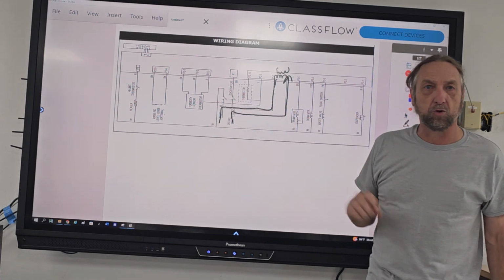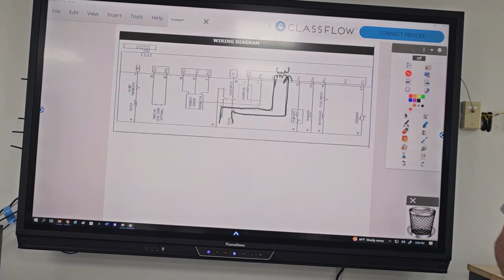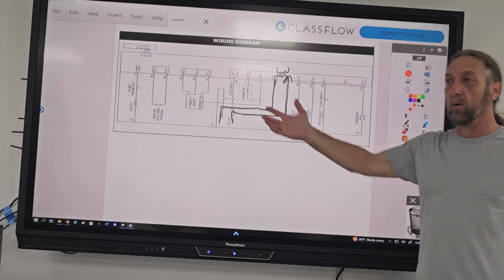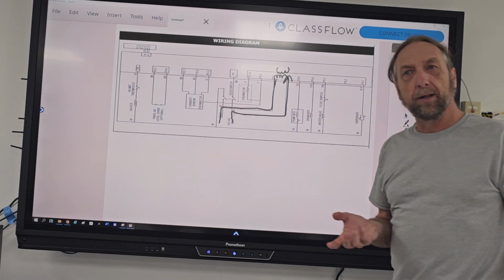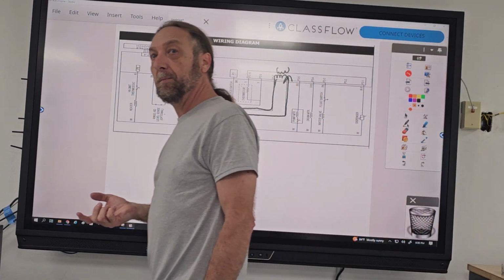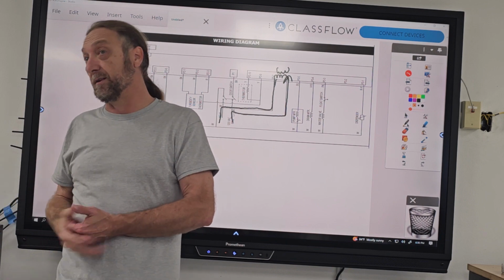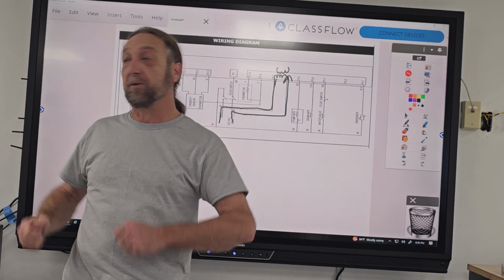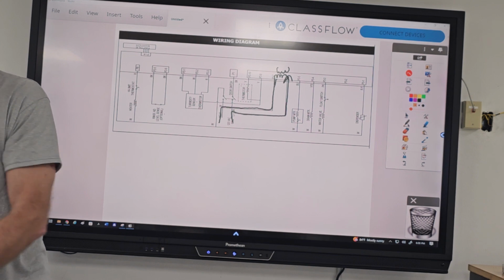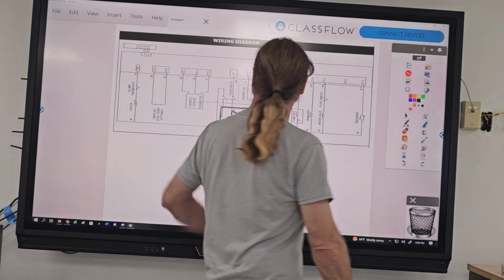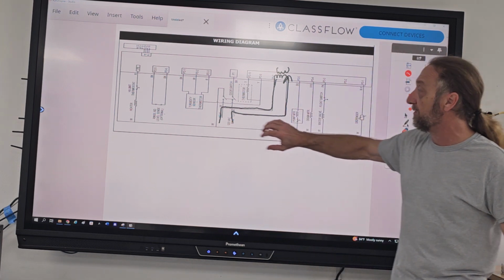Am I going through those door switches now? Did I draw a line through the actual switch? Yeah. Did I go through that door switch? Oh, no. So we don't want it to go through the door switch at that time, because if you're in the middle of a cycle and it just started, let's say running 3 or 4 minutes, you're like, oh man, I forgot to put these plates in the dishwasher. You open up the dishwasher. Once you open it, these 2 door switches open. What happens to all these parts?